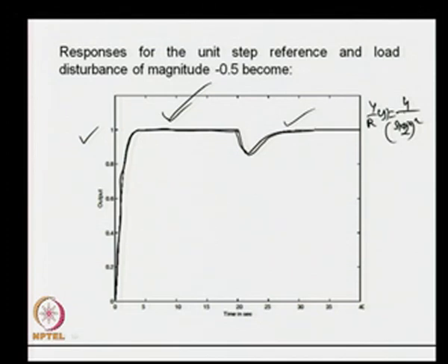Since the overall transfer function is found to be of this form, the response of the system in time domain can be expressed as y(t) equal to 1 minus e to the power minus 2t, then minus 2 e to the power minus 2t times t. So, this can come in this form, approximately this will be of this form.